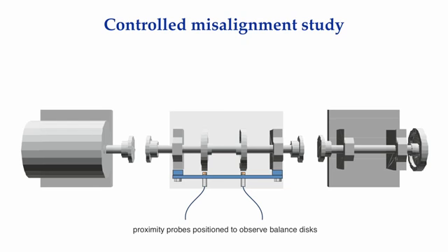The motor, center shaft, and outer shafts were aligned within 0.2 of a mil per inch in both the vertical and lateral directions. I then started the drive system up and, using an accelerometer with a magnetic base, measured the amount of vibration on the bearings on the motor, center shaft, and outer shaft in the vertical and horizontal directions.